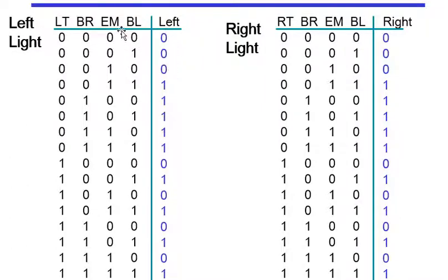Now, if we apply the emergency signal right here, the output is displaying a high when there is a high pulse on the blinking and a low when there is a low pulse. Now, if we apply the brakes, the brake overrides the emergency right here and displays a constant 1 throughout in this area. Now, if we apply the left turn signal, it has to show a constant blinking, which is why we have followed the blinking in this output.